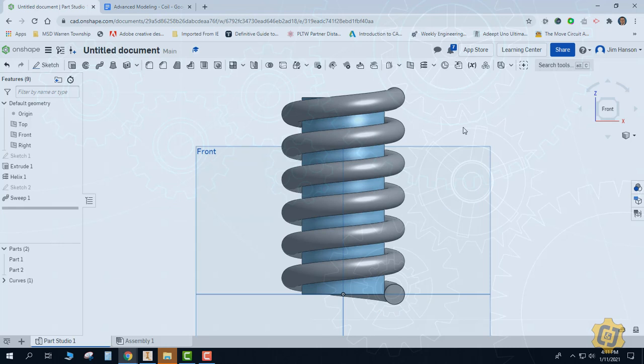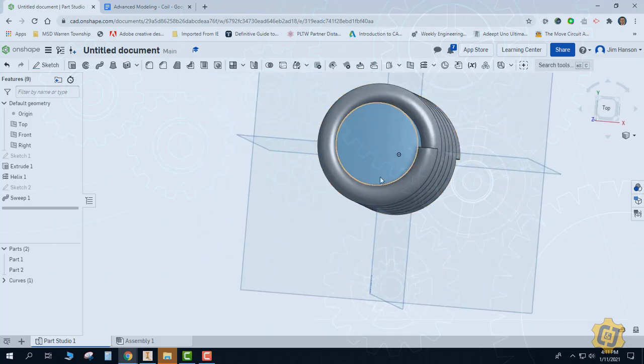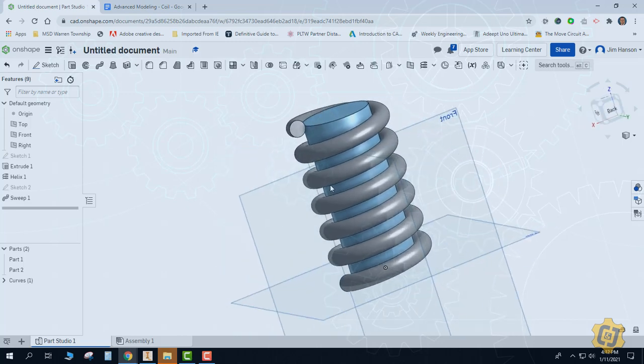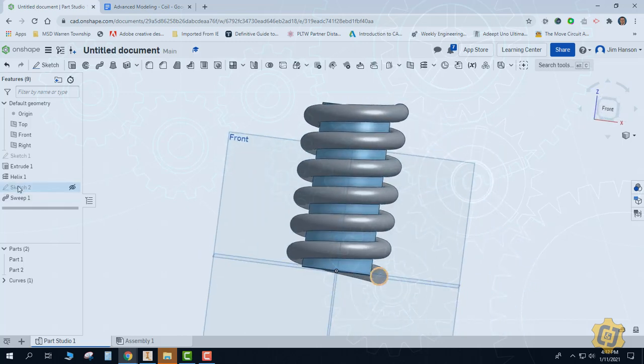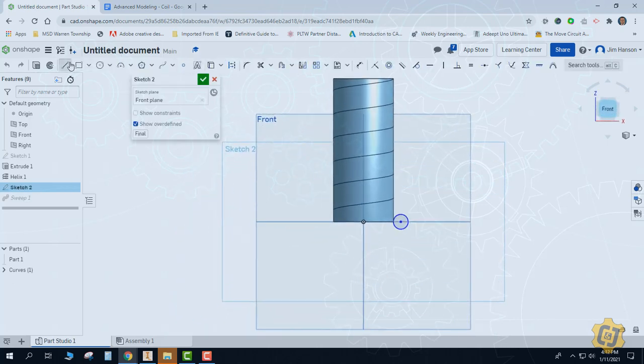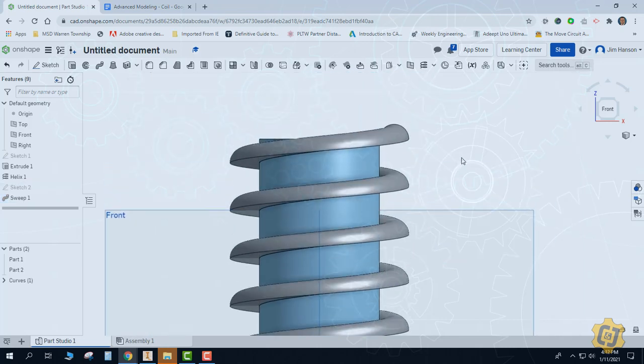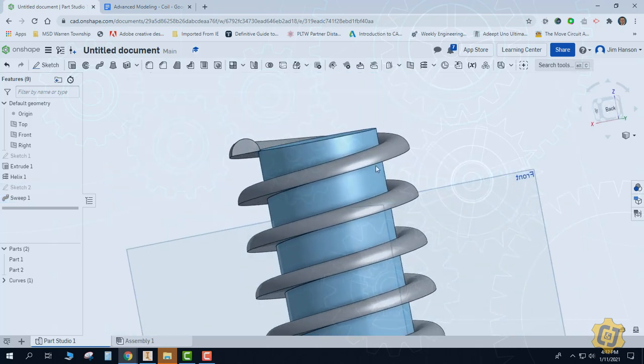So now that blue cylinder truly is a core. It is now the inside diameter of the spring that I've got. So if you're using the defaults that are currently there, you have to go ahead and understand a couple things about it. Number 2 is the height. When I went ahead and coiled this, you can see that I actually have part of my circle living below the coil as well as above the coil. And even if I had cut my circle in half, I still would have had that other half of it go past the object.